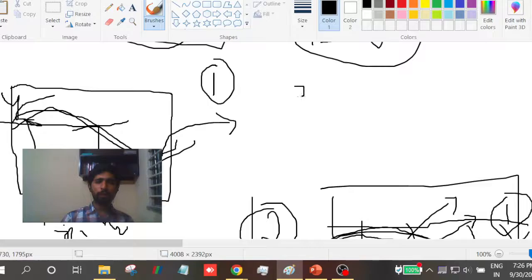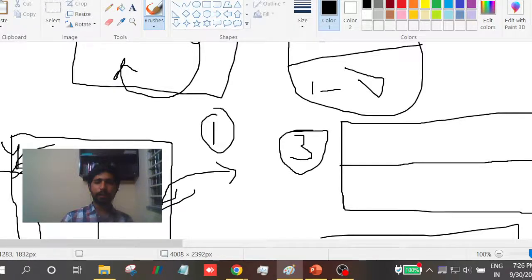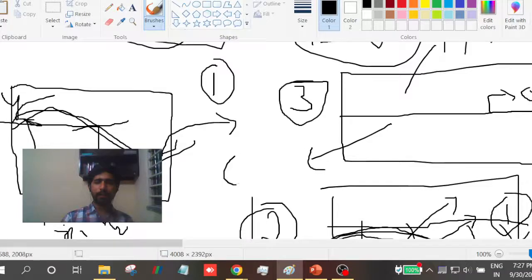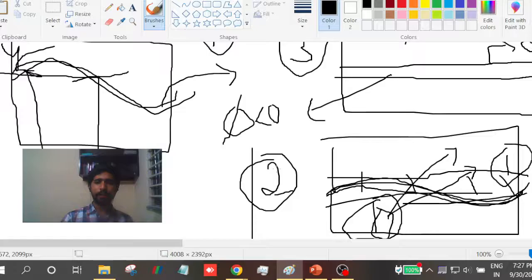So usually we go with a diffused approach, wherein there is a slow transition, and at this interface we usually have a fixed value of the function to be 0, which is usually called the level set method. This is a third approach to capture the interface, okay. And then here it slowly goes away from 0, and in the other phase also it goes slowly away in the opposite direction. It is not just a direct jump which was happening in the heaviside approach, okay. So that is the difference between approach number 2 and 3, that is level set and this heaviside function approach, okay.